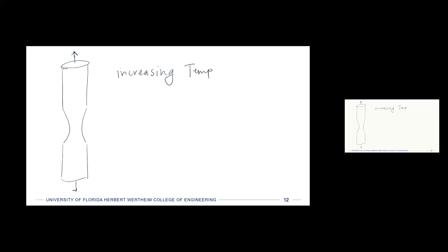And so if you have a uniaxial creep test, right, and you have like your little section in the middle that's reduced in diameter so that that's what you're measuring, you put this in here. Okay. With increasing temperature, there are a variety of other factors that are changing simultaneously. So if we have increasing temperature, like we saw sort of going to the right on that other diagram, right, the ultimate strength of the material drops. So, okay, we know there are some ramifications on that.